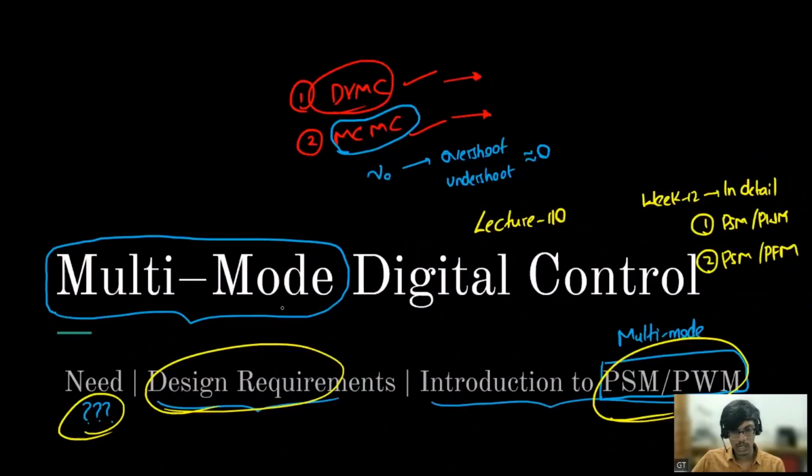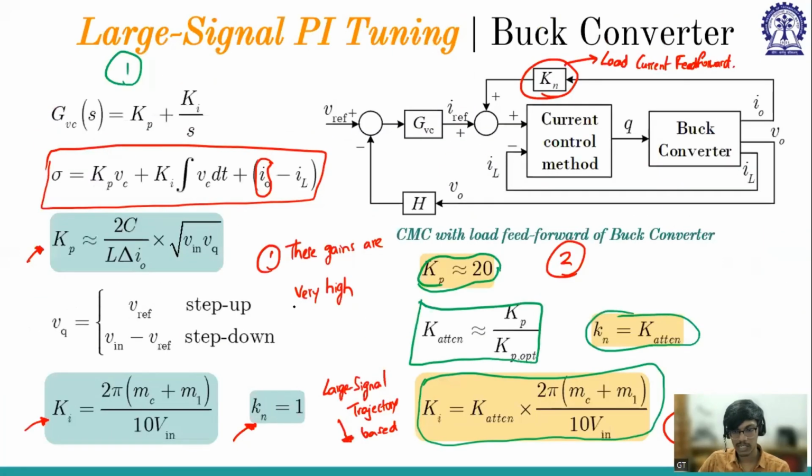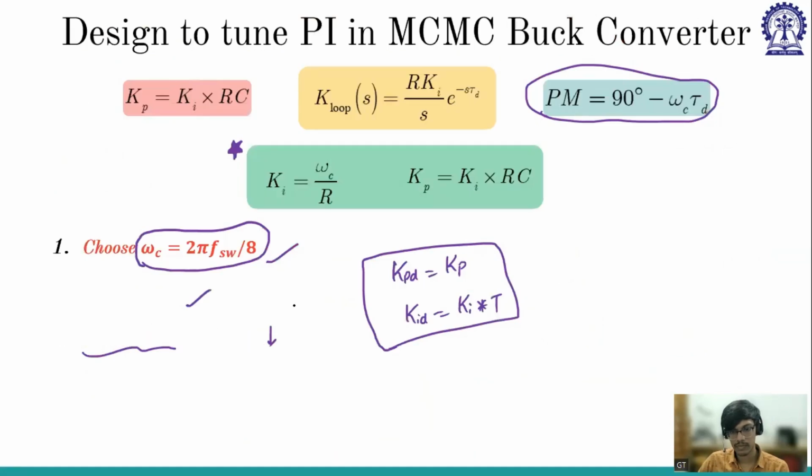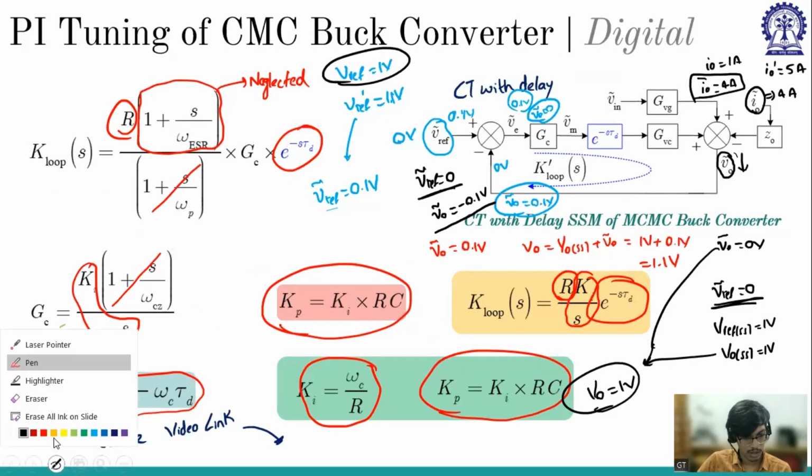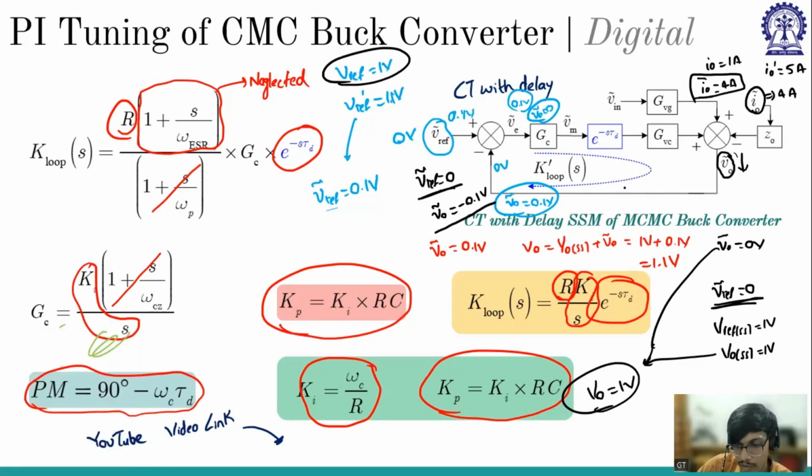So let us consider another case study where there is some disturbance, noise. Say there will be a feedback gain here, right? Say some noise n perturb has been added in the loop, which will change this value, which will change this value, and because of the noise, say my V0 perturb has become 0.01 volt.